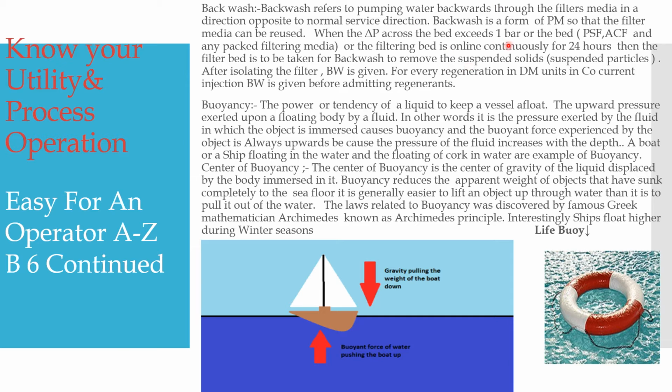So backwash plays a vital role in a water treatment plant. If the delta P across the bed increases within 10 minutes also, then it will be isolated and given a backwash for a short while, then it can be taken online to resume to get more flow. So backwash plays a vital role in water treatment.